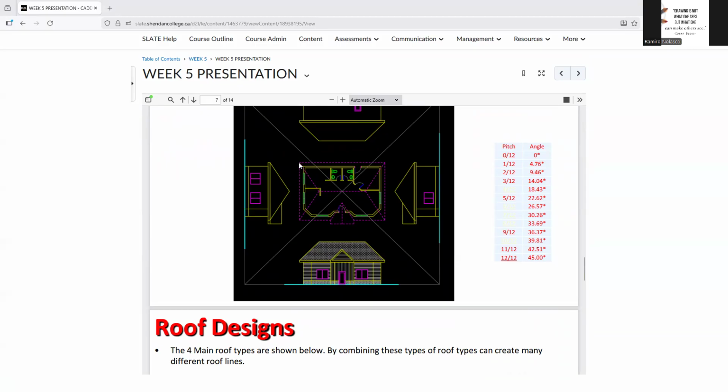Okay? So, again, notice this is not at 45 degrees. I don't prefer that. I don't like that. This is about 30, 60, right? Now, why 45 degrees? It's a lot easier for carpenters to create a miter joint, 45-degree angle, than a 30-60 on site.